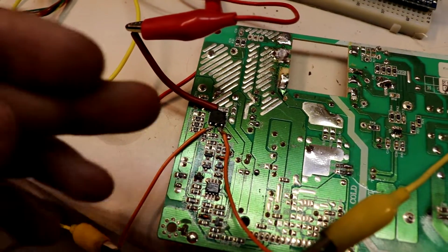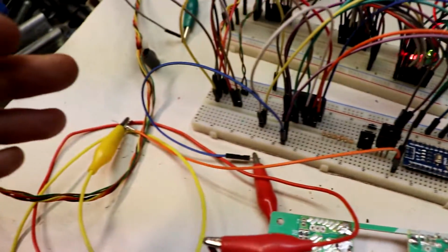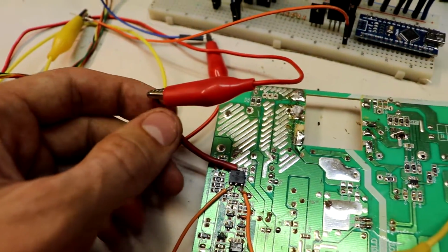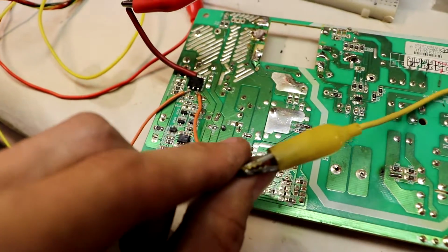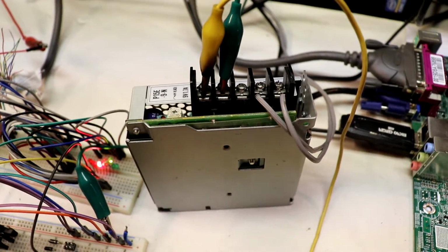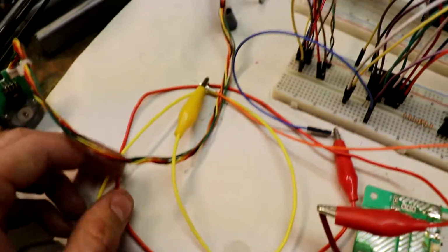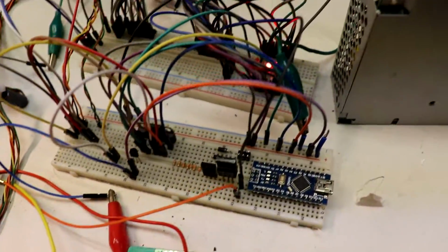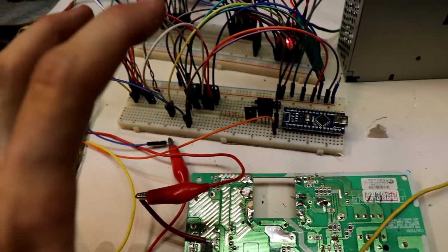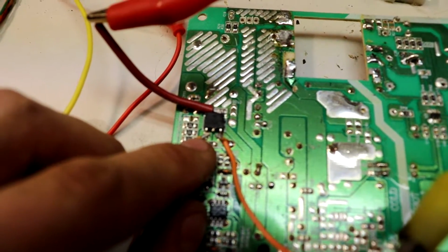But in any case, it was suitable because I hooked up one of the breadboard wires to the positive terminal, and I routed that through the drain of the MOSFET, and then this is the source, and I routed that over to the power supply. The power supply is giving like 11 volts of power. And then for the gate that's over here, I actually connected that directly over to pin 3. And so in this way, the power is interrupted. All the power that goes into the motor controller is interrupted by this small N-channel MOSFET.